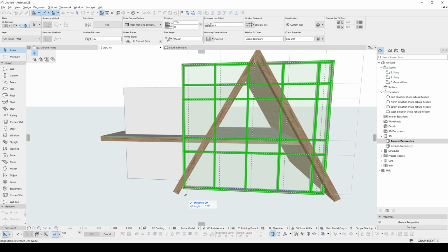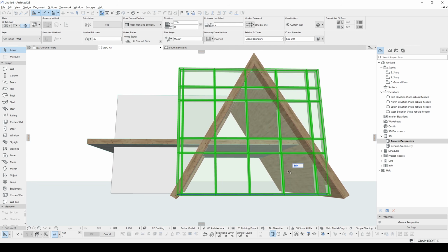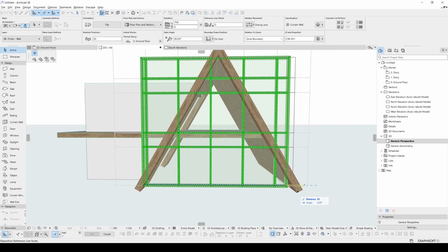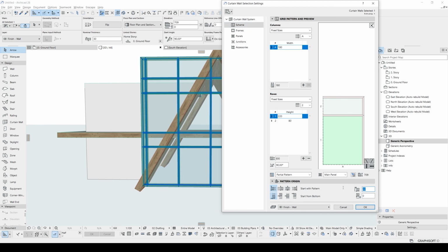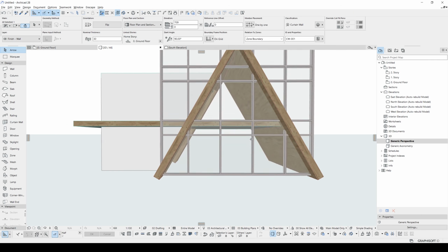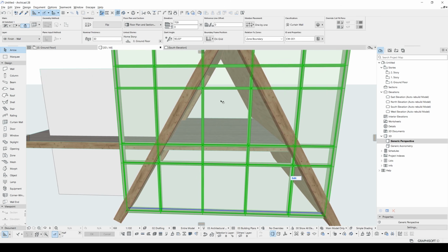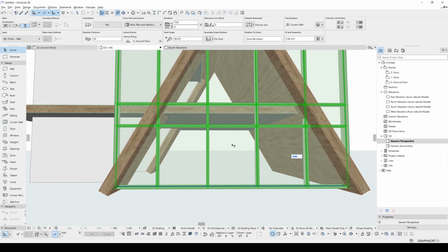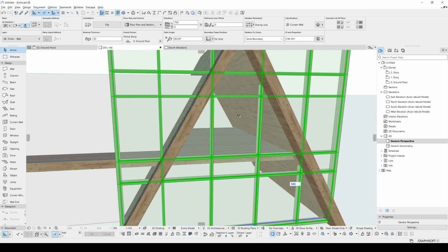Before that, I want to match the inner points to inside of the roof. And we will make this 0 and we will click this start from center. This is going to start from bottom, but for the horizontal placement, vertical placement, we are just going to select this middle of the segment. Yeah, there we go. This is going to be our door and other window and door.